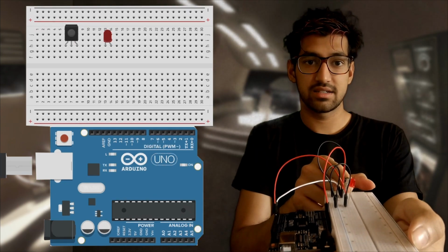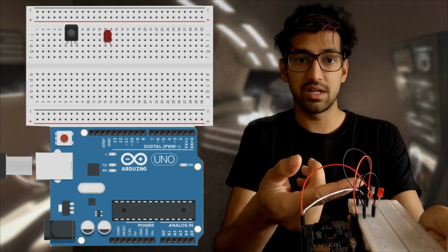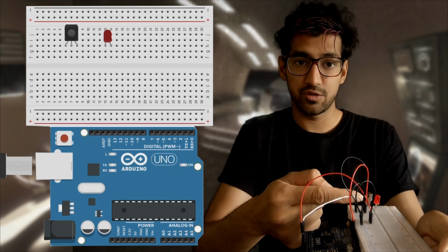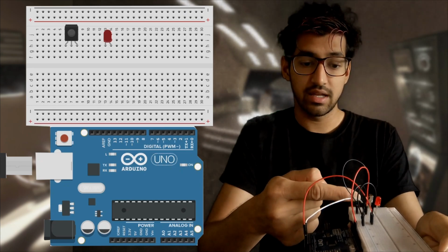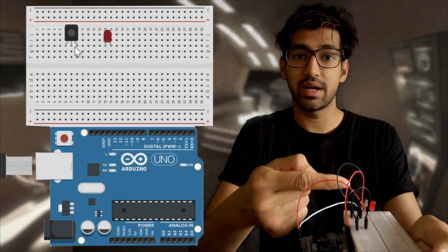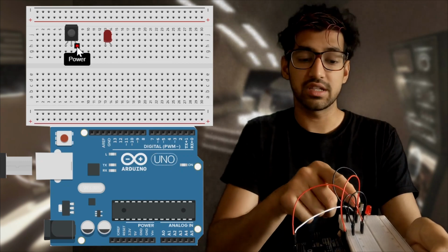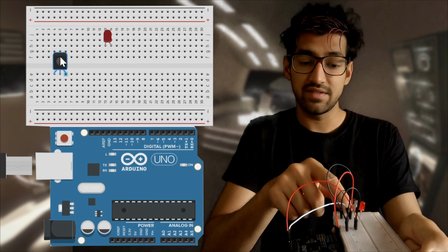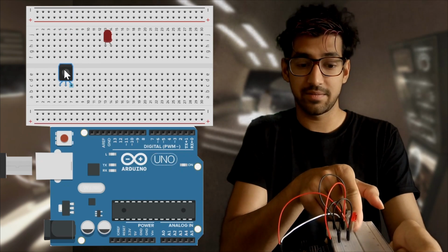Connect the infrared sensor in such a way that the black bulb structure is facing towards you. In that way, the leftmost port is the sensor port, the middle one is the ground, and the right one is the positive port for the infrared sensor. Connect the infrared sensor to 5C, 6C, and 7C.